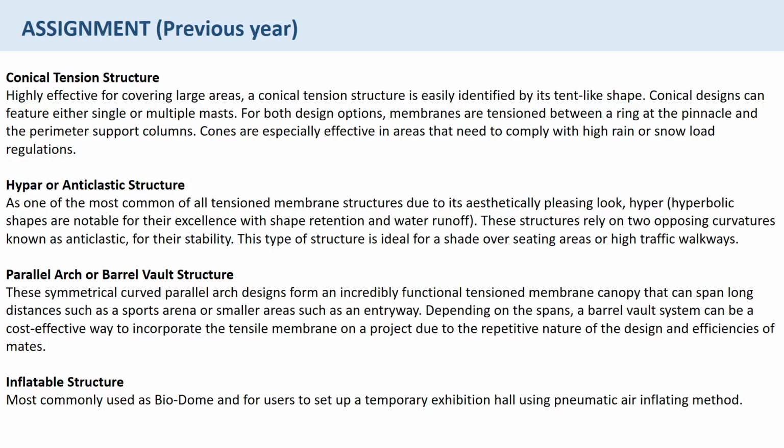Parallel arch or barrel vault structure. These symmetrical curved parallel arch designs form an incredibly functional tension membrane canopy that can span long distances such as a sports arena, or smaller areas such as an entryway. Depending on the spans, a barrel vault system can be a cost-effective way to incorporate the tensile membrane on a project due to the repetitive nature of the design and efficiencies of materials. Inflatable structure. Most commonly used as a biodome and for users to set up a temporary exhibition hall using the pneumatic air inflating method.